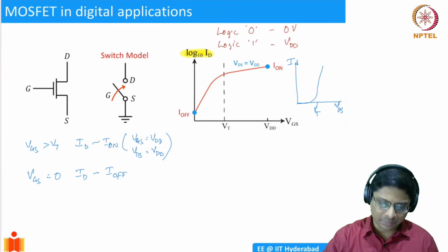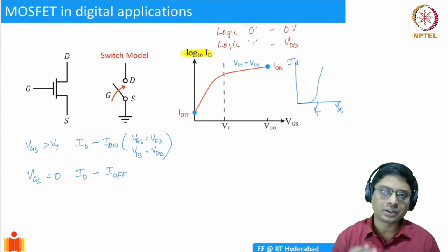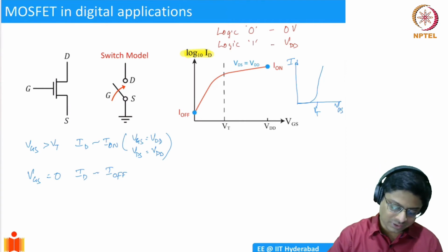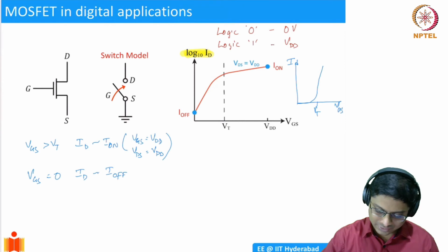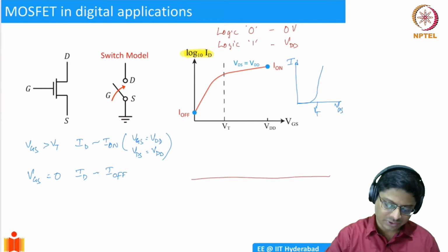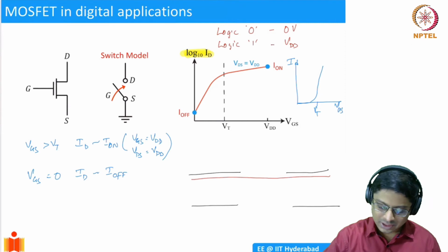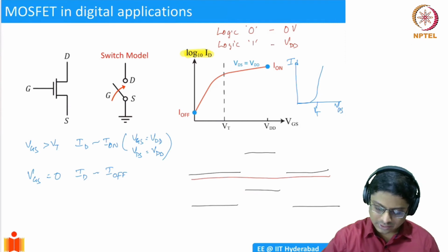And it is not quite surprising if you think about it. What is the reason for how the gate is actually controlling the drain current? Well, always go back and remember this physical picture wherein you have a constant Fermi level, and then you have the source and then the drain, and in between you have the channel, right? So we saw that there was a barrier forming here.